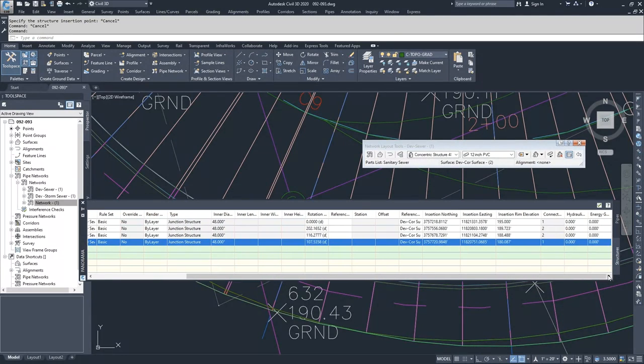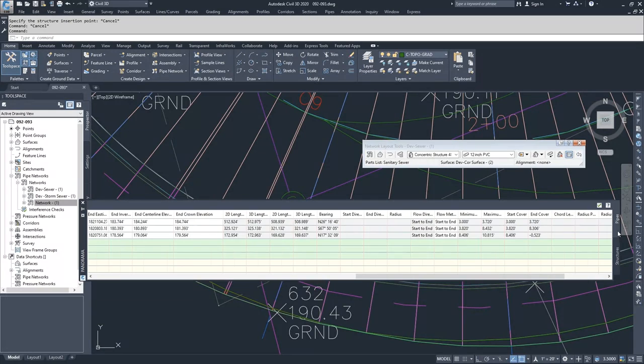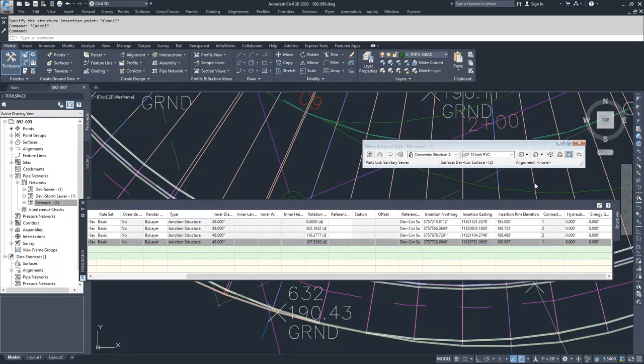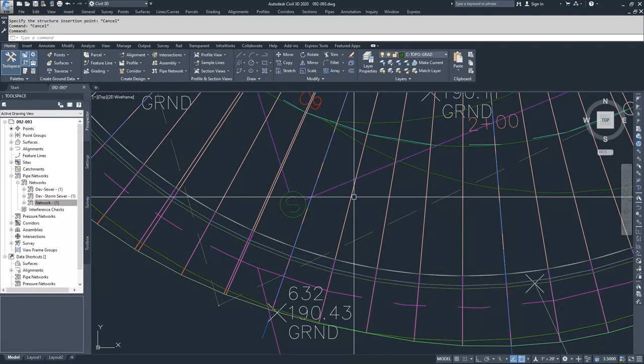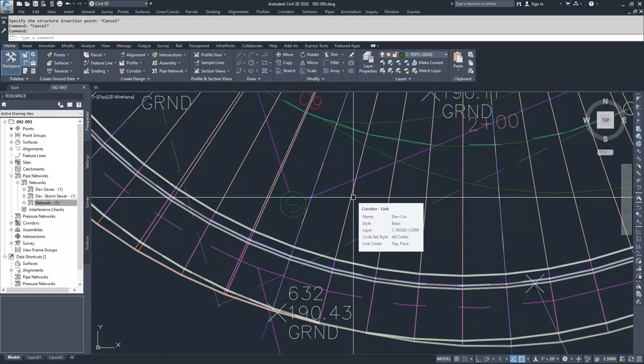And then moving from there, you have two tabs. You have your structures tab and your pipes tab. So you can navigate between the two and choose the options for all of your pipes or all of your structures, and then accept them by checking the green check and closing out. And so any changes you would make would then be translated into the drawing.